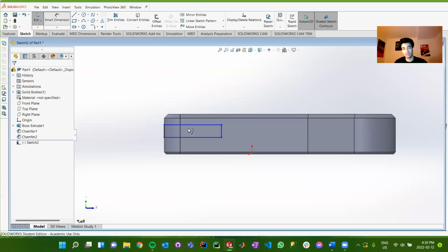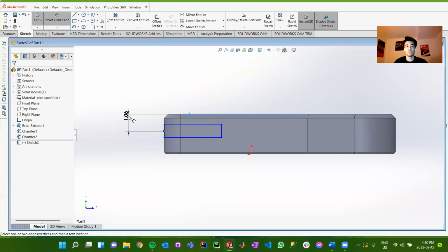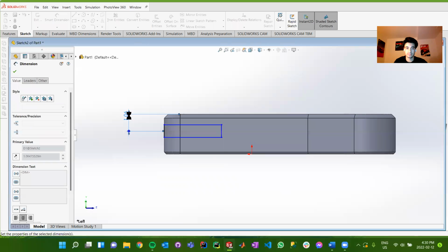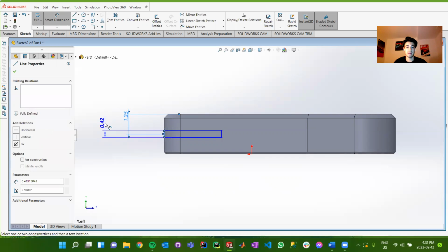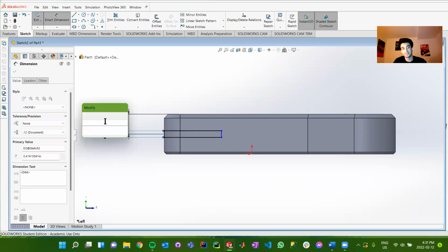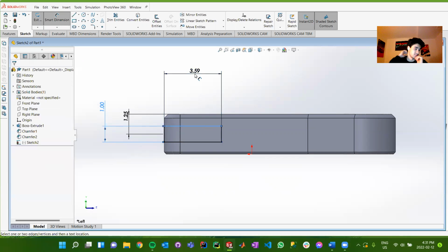And then from there, I'm going to just draw one simple rectangle. Cool. And I essentially want it such that the center point of the rectangle is 1.25 inches, or halfway down from the top of our object. And then we'll also specify the width of the actual selection itself. So let's say it's going to be 1 inch wide. Awesome. And then we've got to specify a length. So we'll give this a length of 2 inches.